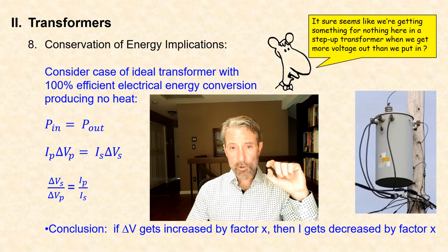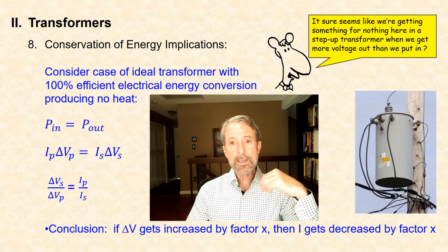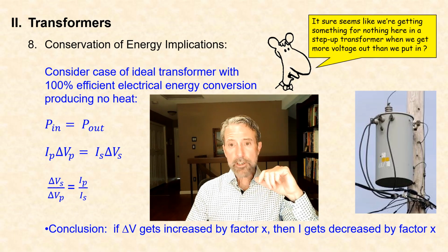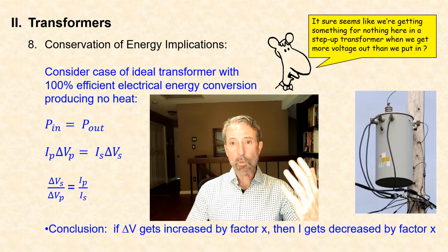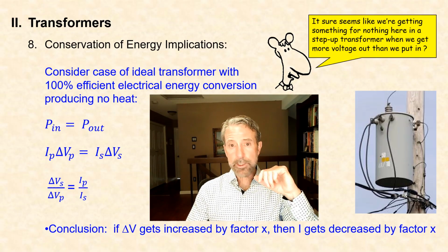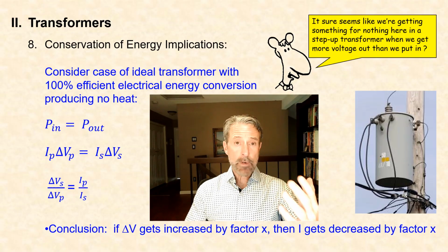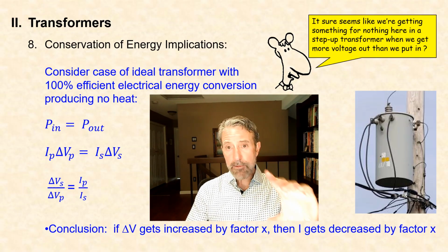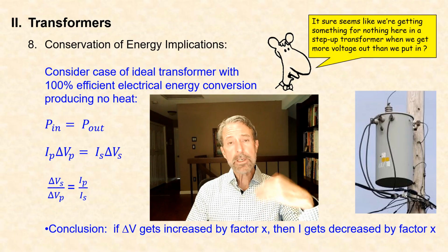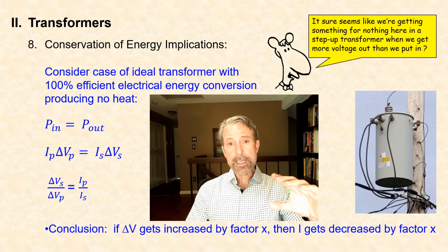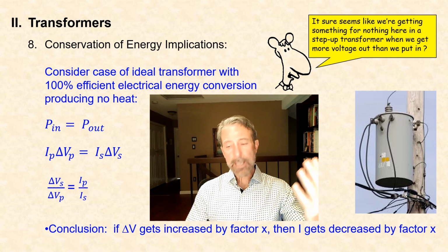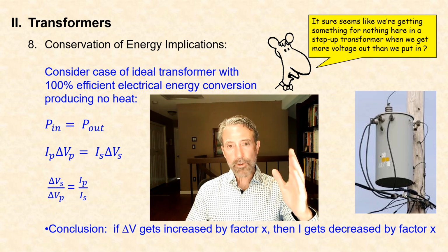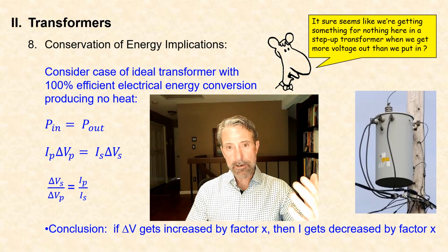So that when transmitting power with AC, the above equation tells us that we can basically trade off voltage for current. So transmitting electrical energy at a high voltage and low current has the effect of reducing that inherent I squared R power loss, which is the loss of useful electrical energy to the form of thermal energy.